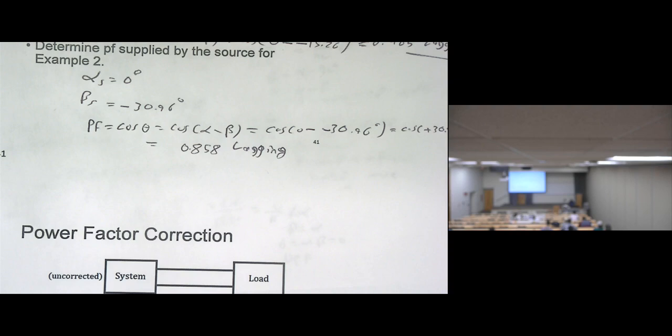Are these inductors leading or lagging? When we talk about inductors, lagging. That's why in real life, most of our applications are lagging. So when we have a large amount of motors in a certain factory, a large amount of lagging, this will make the power factor poor, lower and lower. Sometimes you can see the power factor is about 0.6 or 60%. This will affect the grid, and it will not be cheap.